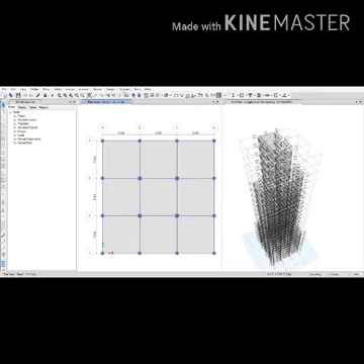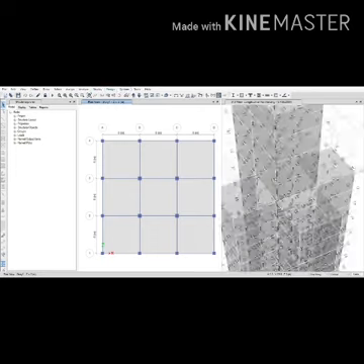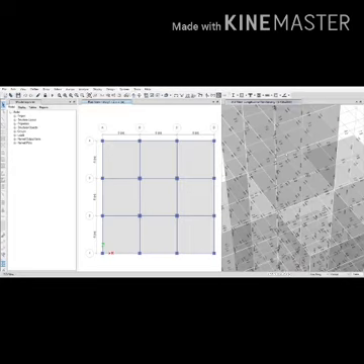So finally, you can view the different bar material detailing in this. And if you go to the ETABS concrete frame design, you can see there are different reports: summary, flexural details, shear details, envelope details, and the expected frame sections. Everything can be found through this for different things. And click OK.